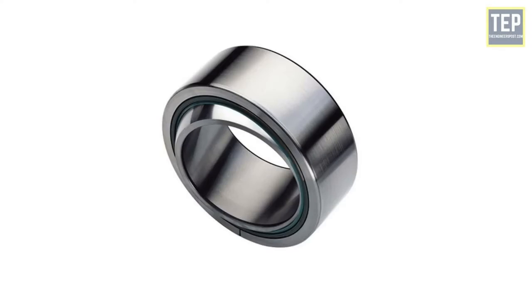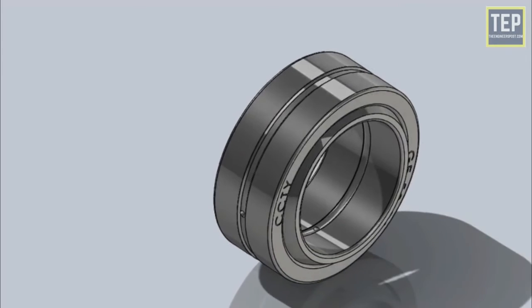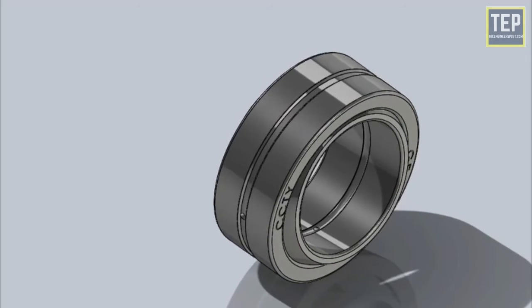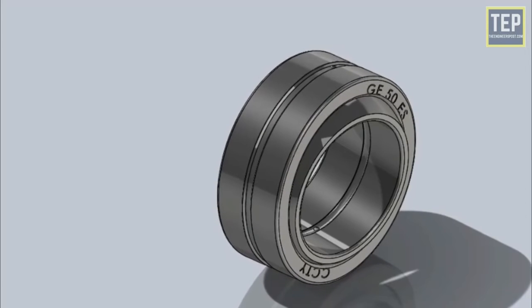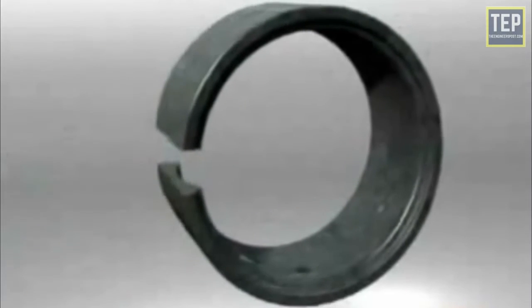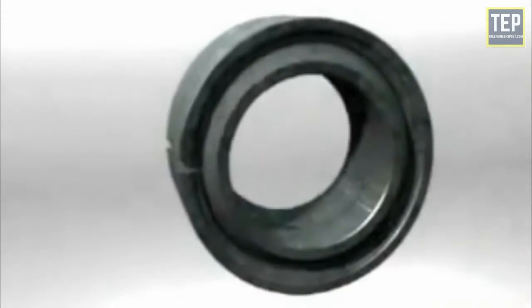A plain bearing is the simplest type of bearing. It usually only consists of a bearing surface. There are no rolling elements. Plain bearings are used for rotational, sliding, reciprocating, or oscillatory motion. The bearing remains fixed while the journal slides on the bearing's inner surface. The bearing is basically a sleeve mounted on the shaft and fit into the bore.